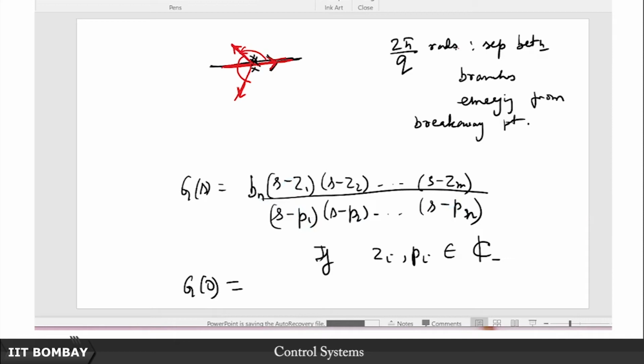So it turns out we should only be bothered about those poles and zeros which are on the real axis, the real poles and zeros and their signs. If the real poles and zeros are all on the negative real axis, the left half plane, then this g0 is positive, and this serves us well. Why do I say that?